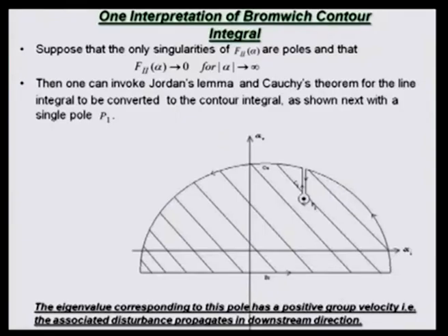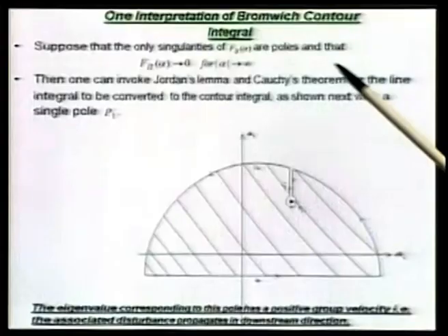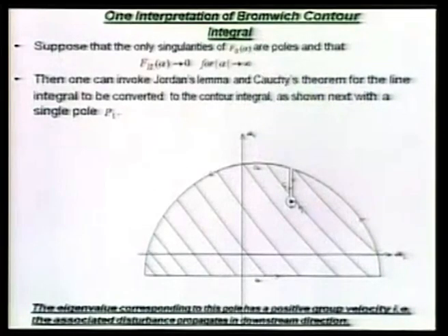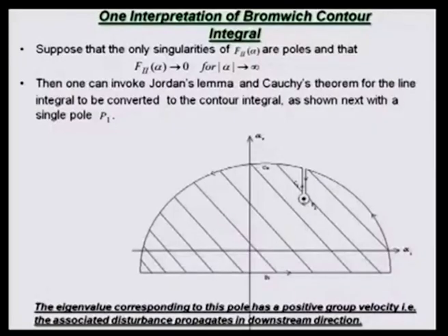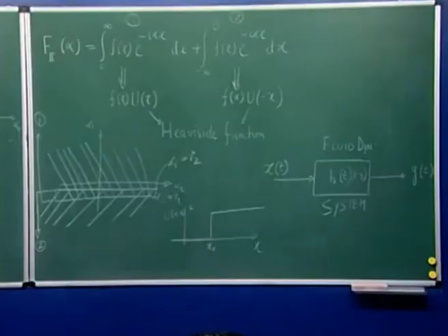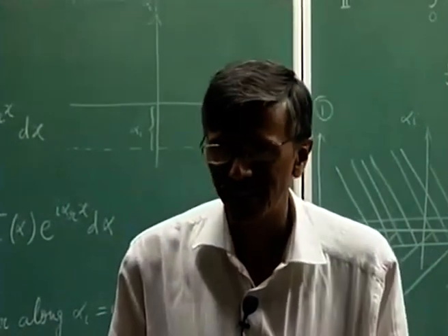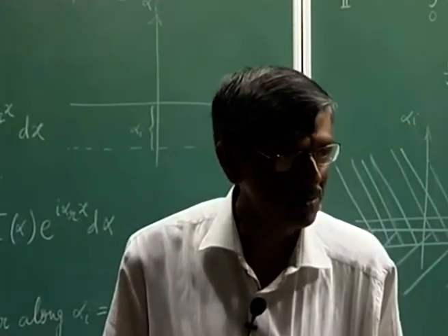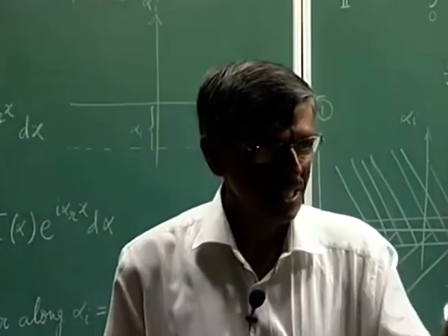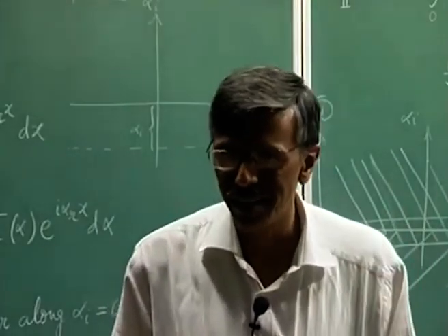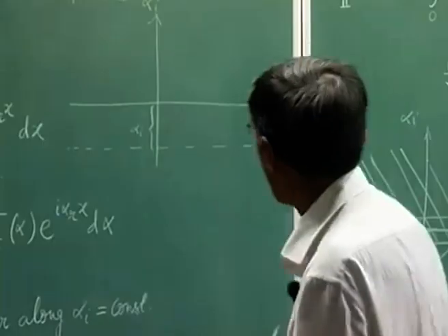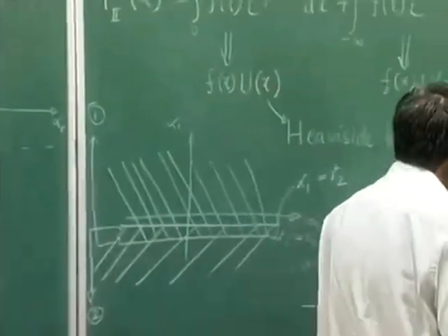Now, this quantity that we are talking about, f 2 of alpha, is something like the phi in the Orr-Sommerfeld equation. You recall that the Orr-Sommerfeld equation is an equation for the Laplace transform of the stream function or the normal velocity that we have established. That phi, that equation that we write, is basically what? A disturbance quantity.